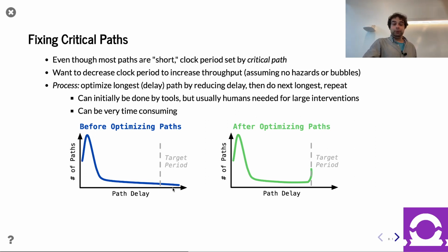Unfortunately, fixing critical paths is really annoying, because by the time you see the timing report, the names don't make sense, because your design has already been synthesized. What you thought was your Verilog or Chisel statements have now turned into a lot of nets and gates, and you have to parse that backwards to your design.